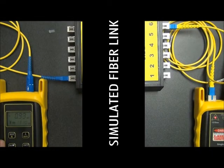And finally, we store a reading for fiber number 6. As you can see, the fiber number kept incrementing from 1 to 2 all the way up through 6. Now, what we're going to do is switch the wavelength on both units. So we simply press the lambda button to do that. We're switching to 1550 nanometers.